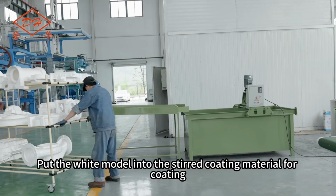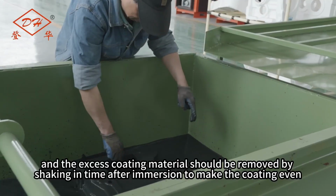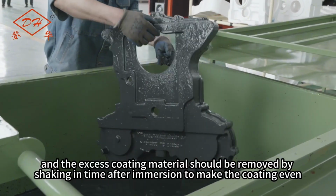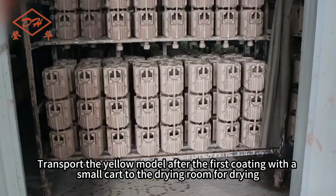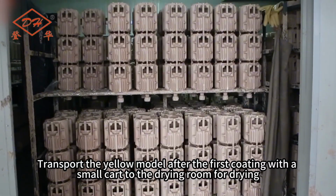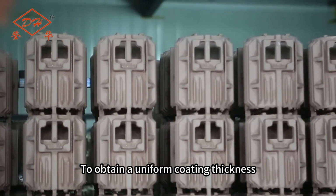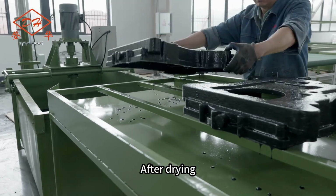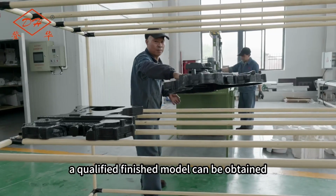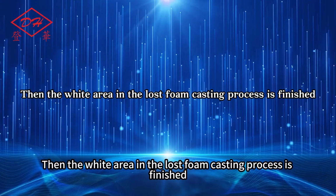Put the white model into the stirred coating material for coating. The immersion layer should be even, and the excess coating material should be removed by shaking in time after immersion to make the coating even. Transport the yellow model after the first coating with a small cart to the drying room for drying. To obtain a uniform coating thickness, a second or third coating and drying can be applied. After drying, a qualified finished model can be obtained. Then the white area in the lost foam casting process is finished.